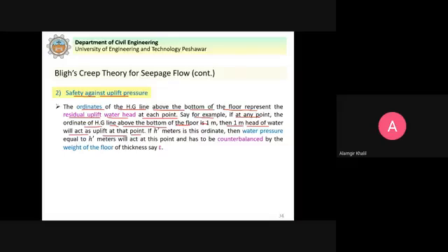This is the same as I already explained before. You have this as H. So we say that the uplift pressure here is also H. And then it will decrease because the water seeps, so there will be loss. And if we have some water here, then it will be a trapezoid. If no water, it will become triangular. So you take from the bottom, this is H here. This is the uplift pressure that will act because of the subsurface water flow.